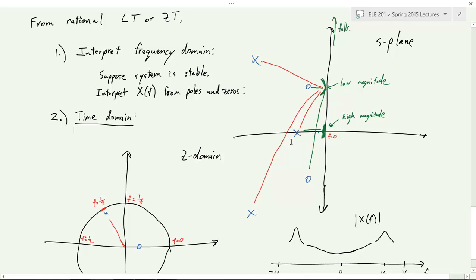And the real part of the pole determines the exponential decay, if you look at that table, right? So the more negative the real part is, the further it is away from the imaginary axis, the quicker that term decays exponentially. Sometimes you want to know, not only is your system stable, but how quickly does it return to 0? 0 represents like an equilibrium position. How quickly does it return? Well, if the poles are further from the imaginary axis, then it is going to respond very quickly. If they're very close to the imaginary axis, meaning you're sort of almost unstable, then it'll stay a while before it dies off. Of course, and what does this imaginary part mean?